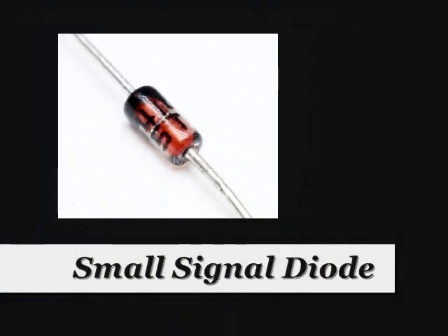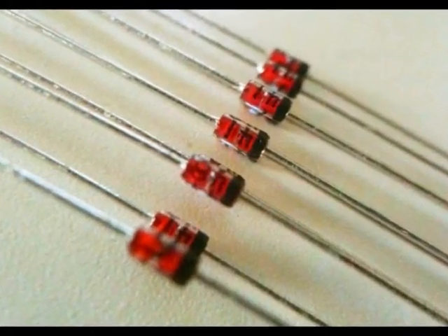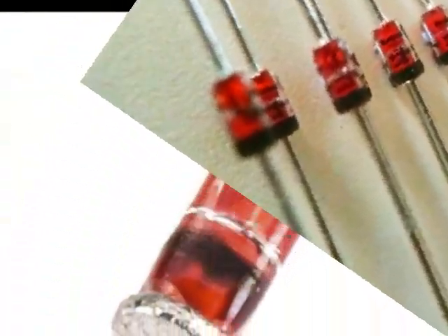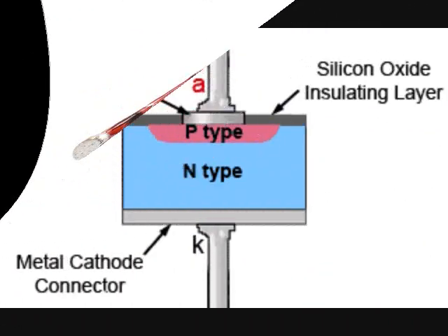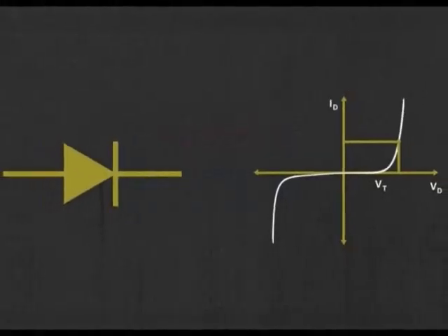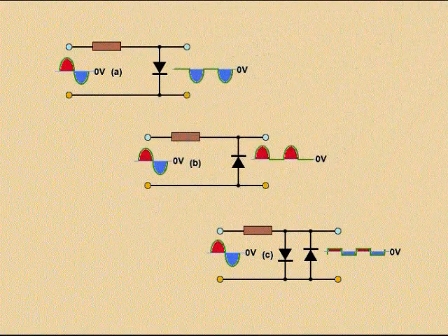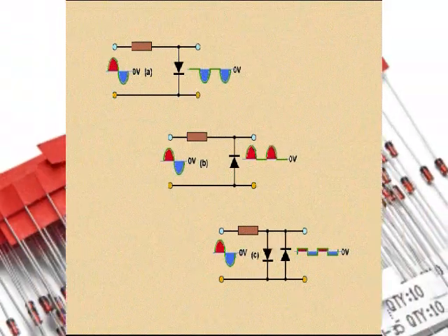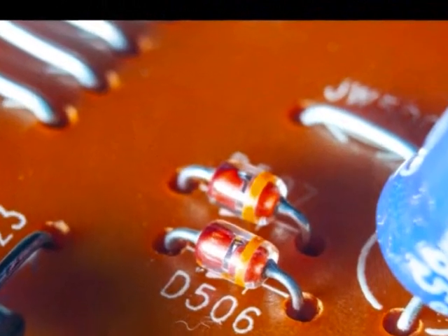Small signal diode. These types of diodes belong to the family of PN junctions, the width of which is very small. For this reason, they are capable of operating at high frequency and high speed switching and work in very low voltage and current ranges. The reason for naming this diode comes from the fact that it works in the range of milliampere current.